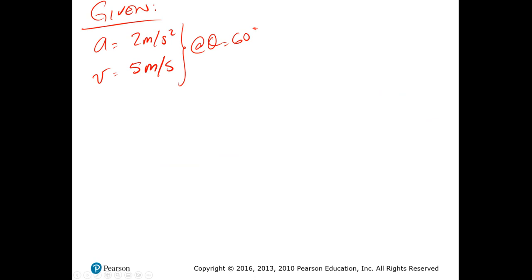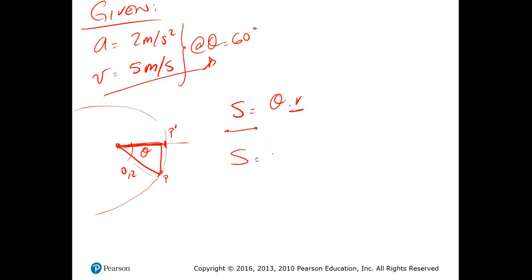This is just for a given interval of time, so we need to find an equation that will work for anything. So we need to relate, like I said, position with angular position. We have the engine that is moving the rod from here, and this is given by theta. Well, we know that the displacement will be equal to theta multiplied by the radius. Which radius? It's given right here. This is 0.2. So displacement, or position, is equal to angular position multiplied by the radius.